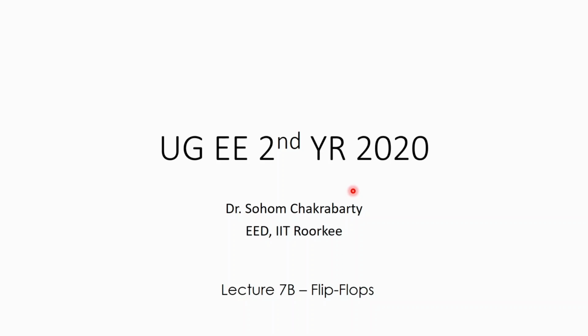So we start with this next lecture of these memory elements that we are studying. After the latches, we ended the latches with an idea of control input, and we are talking about the concept of synchronizing the changes in the output with the changes in the control input. When we are able to achieve that, the same circuit that we saw for the latches, we will call flip-flops. When it is asynchronous in nature, we call it latch. When it is synchronous in nature, we call it flip-flop. And how we make it synchronous, that is what we will investigate here.